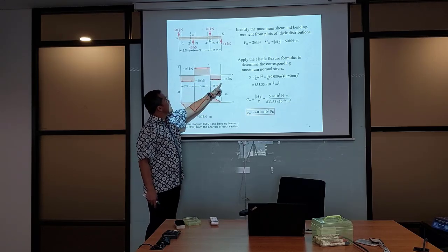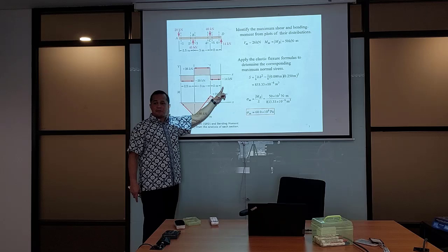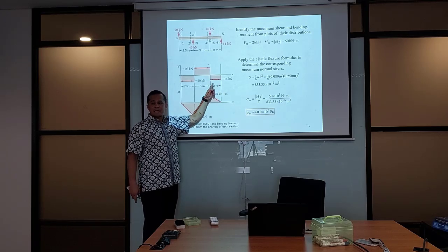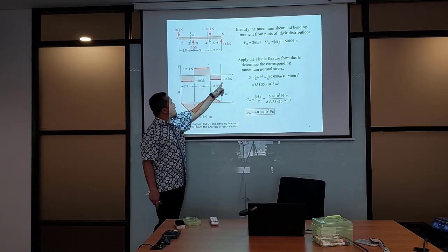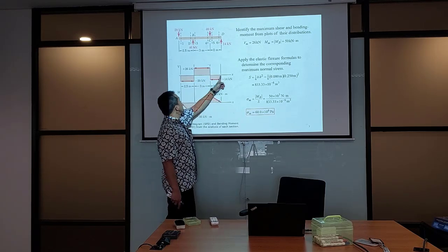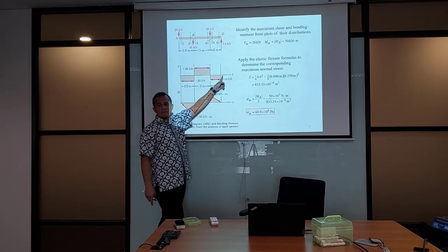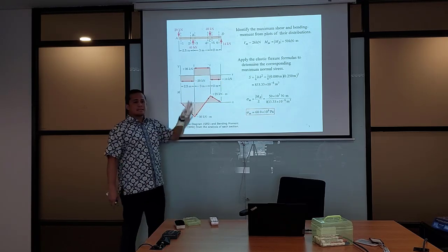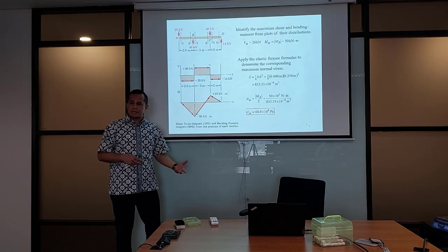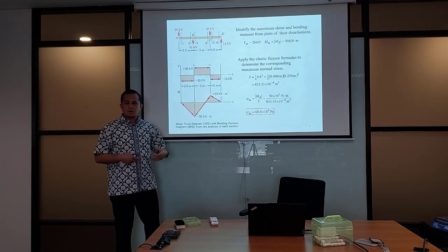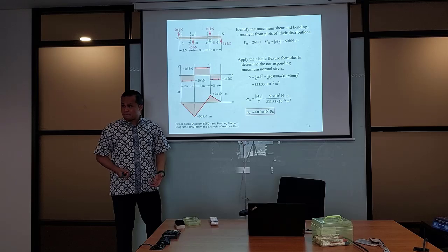Reaching D, you find the final force that will make the system in equilibrium, which cancel the 14 minus, add up by the 14 positive. So start from 0 and end in 0. So that's how the applied load, the transverse applied load, is converted into a shear force diagram.